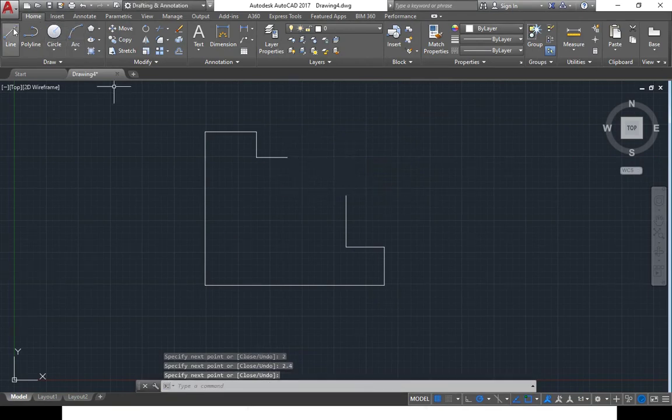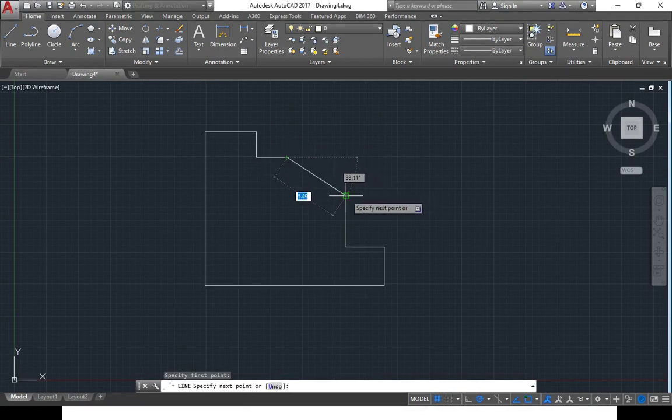Now we can join the lines. Since we don't know the gradient of that line, it's easier to just join the two lines there. When you join those two lines, we can now shape this head part here. We can also shape this part here. And how do we do that? This is the part where you introduce what are called fillets. A fillet is found in this tab.